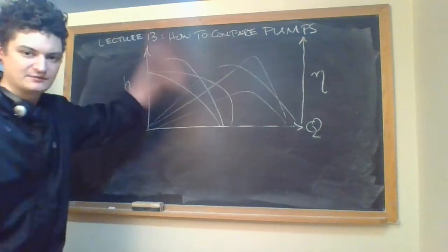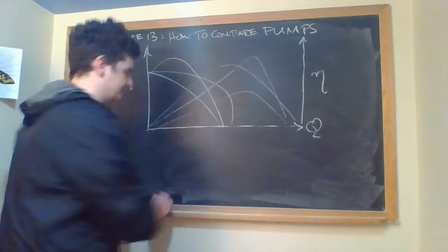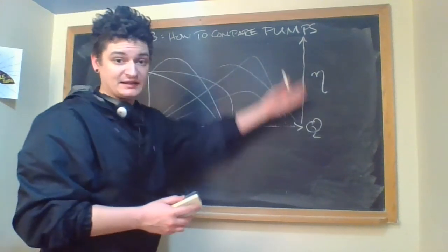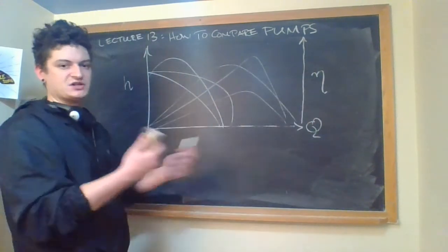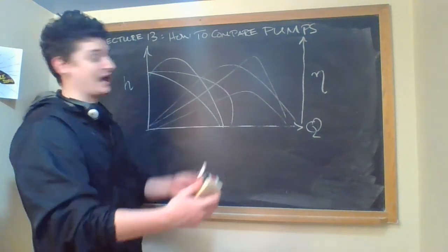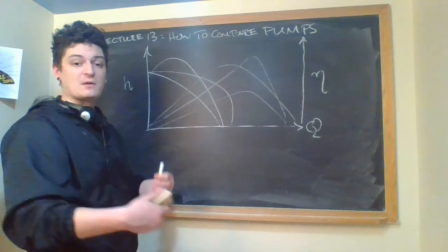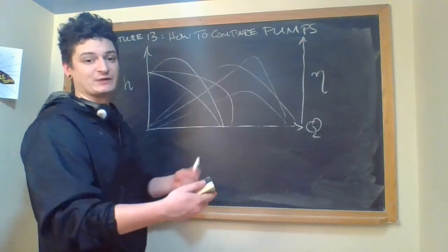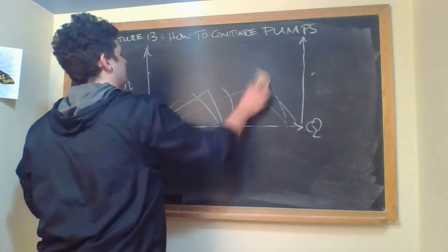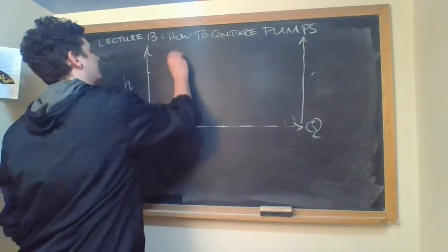So combine these, you want to conjunct all these graphs into a singular non-dimensional quantity. So that's the idea: every pump has a different characteristic curve and a different characteristic efficiency, but by changing quantities like diameter and angular velocity, can we predict what the new thing would look like without actually producing it, without doing that experiment? Can we just do it non-dimensionally? And it turns out it works out. So things we're trying to predict, it's just that.